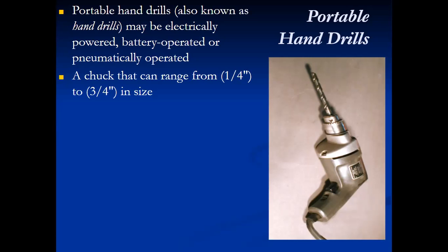If you just had a single hand on a 1/2 inch chuck, and you're running a 3/4 inch drill bit and it caught, there's a good chance it could twist your arm quite hard, potentially causing some damage, maybe even breaking an arm. So we don't want that. That's why those ones have 2 handles, but we generally don't use them in the shop. We have drill presses and we will use those tools, which are much safer than doing this by hand. But we will need to drill some holes at some point, so we do have some battery operated drills for that.